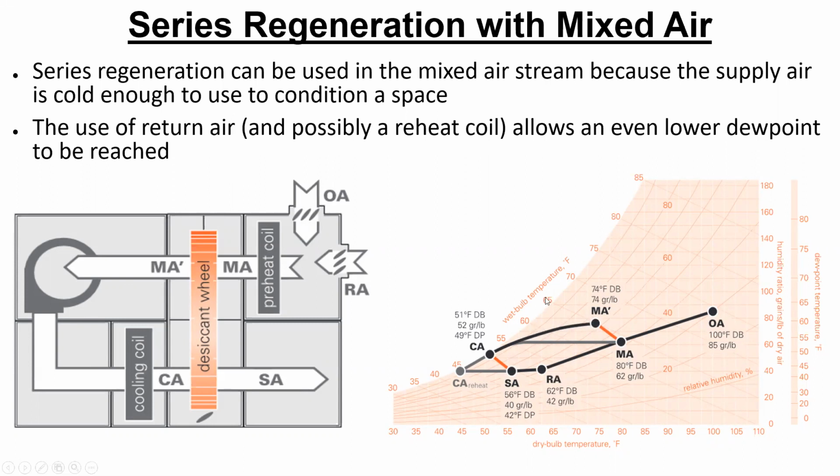We go on this 100% relative humidity. We condense as we go through the cooling coil. As you can see, we're coming down on the specific humidity ratio. And then at the point CA, we can go through the wheel. That's how we do it with the desiccant wheel. We lose more moisture out of it, but we gain some heat.